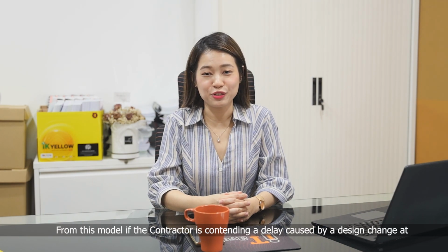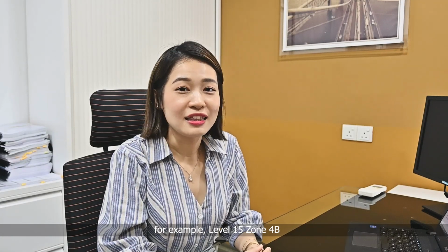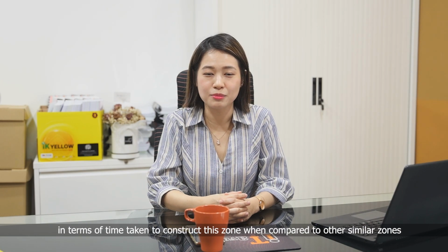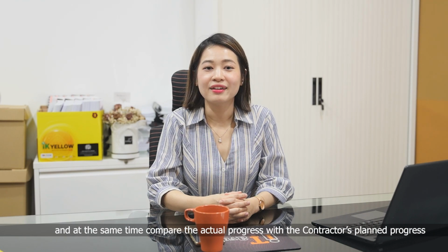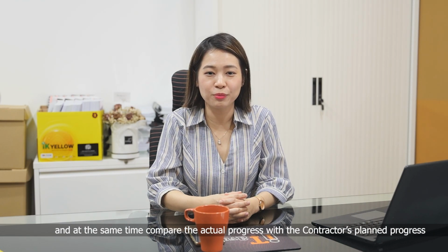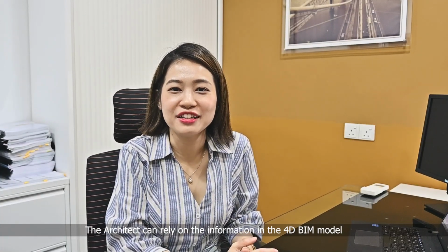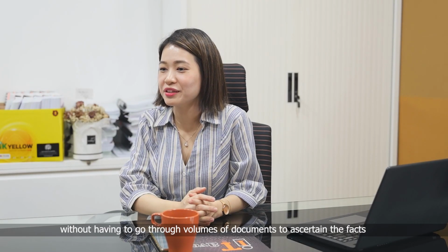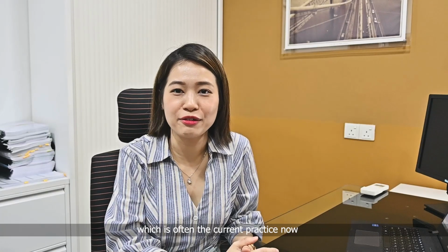From this model, if the contractor is contending a delay caused by a design change at, for example, level 15 zone 4B, from the as-built 4D BIM model, the architect can see whether there are differences in terms of time taken to construct the zone when compared to other similar zones, and at the same time compare the actual progress with the contractor's planned progress. The architect can rely on the information in the 4D BIM model to make a timely decision on the contractor's EOT application without having to go through volumes of documents to ascertain the facts, which is often the current practice now.